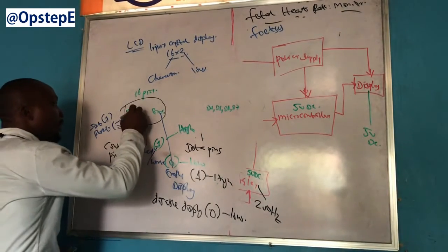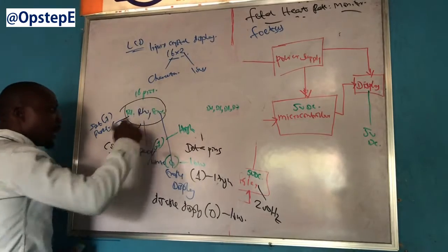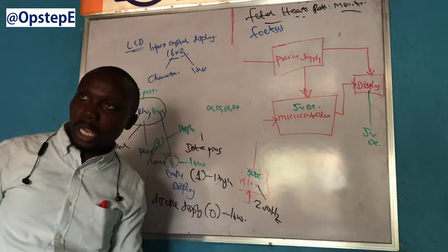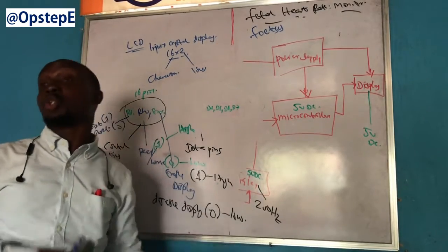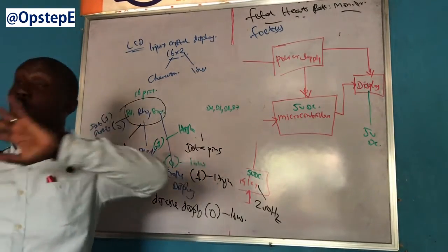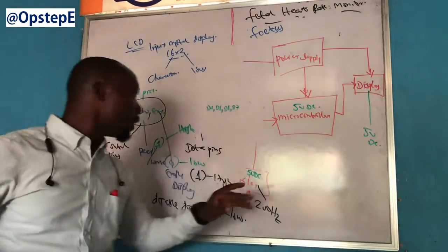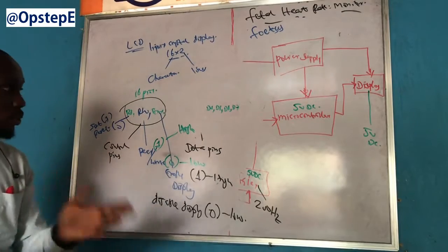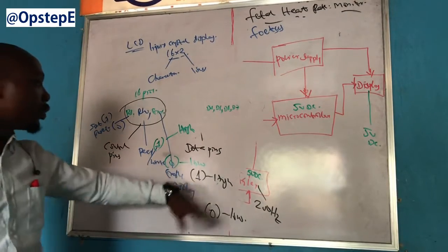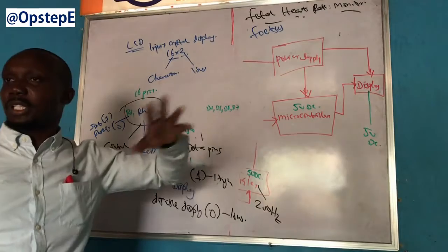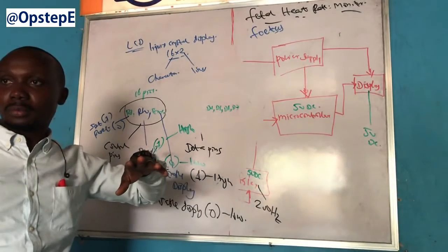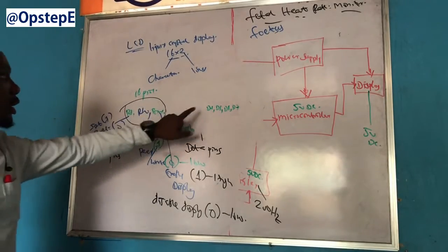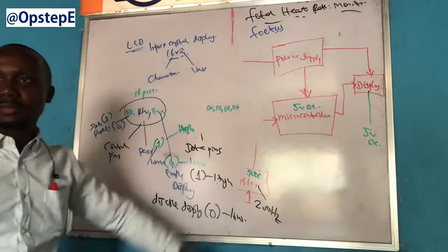For both the RS, the RW, and the EN, while you are issuing command, and while you are actually issuing your data or the signal you intend to display, the state of these pins will be changing from 0 to 1, 1 to 0, 0 to 1, 1 to 0, 0 to 1, 1 to 0. While your data lines will do what? We are having the characters that it should have. So that is the relationship between the RS, RW, EN, D4, D5, D6, and D7.